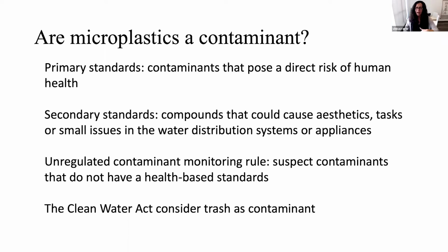So microplastics are not in either of these two regulations for drinking water. Even for drinking water, we don't really regulate them. Microplastics don't fall in any of the categories. However, there is a category called the Unregulated Contaminant Monitoring Rule, for suspect contaminants where we are not sure that they produce some type of health risk. There are discussions in EPA to put microplastics into this category. That means they are going to start collecting data about the amount and type of microplastics present in mostly water for consumption.